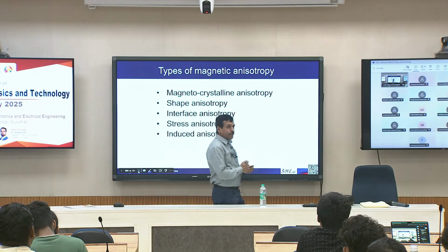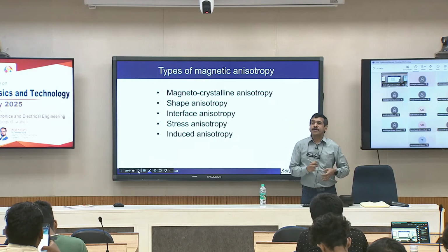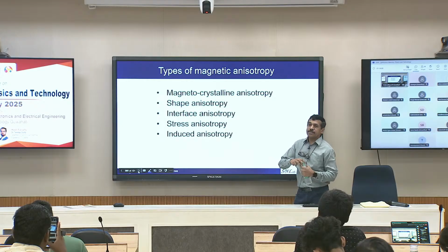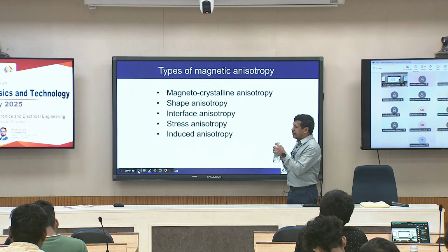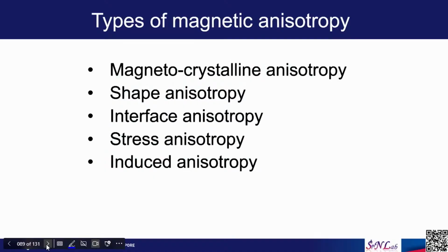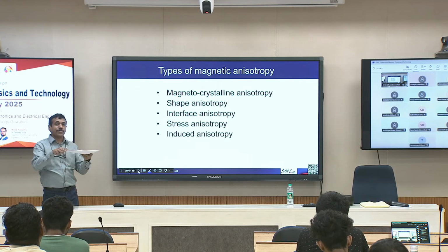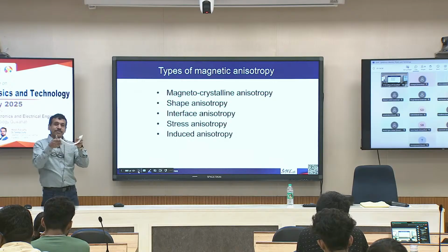Okay. So, we learnt about what anisotropy is. Anisotropy is the property of a magnetic material being different based on the directions in which you measure the magnetic property. In the case of the car analogy that I gave, the anisotropy came because of the topography. In one case you have a flat road, in another case you have a road with some curvature.